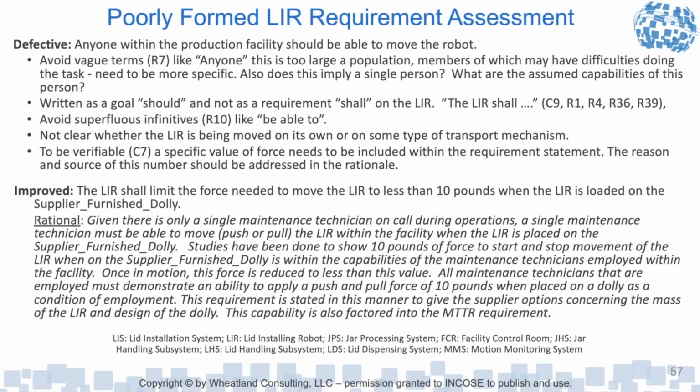Studies have been done to show 10 pounds of force to start and stop movement of the LIR when on the supplier furnished dolly is within the capabilities of the maintenance technicians employed within the facility. Once in motion, this force is reduced to less than this value. All maintenance technicians that are employed must demonstrate an ability to apply a push and pull force of 10 pounds when placed on the dolly as a condition of employment. This requirement is stated in this manner to give the supplier options concerning the mass of the LIR and the design of the dolly. This capability is also factored into the mean time to repair requirement that's defined later.